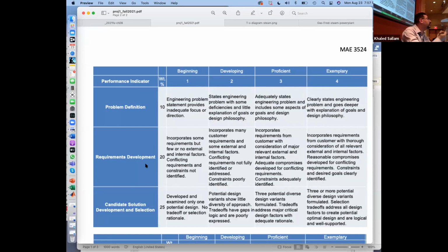You have to be able to get the information yourself, rather than always going to your professor and saying, I don't know, what is it? What should I assume? You will find out what is safe for quality at the exit of the turbine, and you would cap yourself to it. So you will say, I'm not going to run anything that makes my quality less than, say, point whatever.